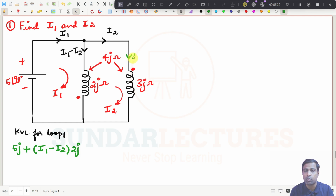This is current I2. So you see here, this I2 in this coil, it is entering. Here this current is leaving. Here this current is entering. Try to understand. So what do I have to put here? I have to put minus because the current is leaving here. The current is entering here. And what you have to write? The second coil's current and multiplication of this mutual reactance. So it is 4j I2, right? That's all we have written. So no other components are connected, so it is equal to 0.